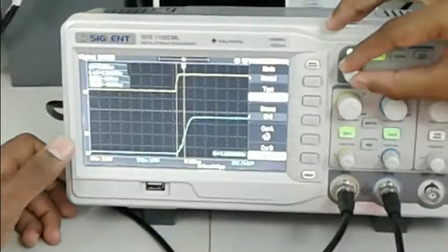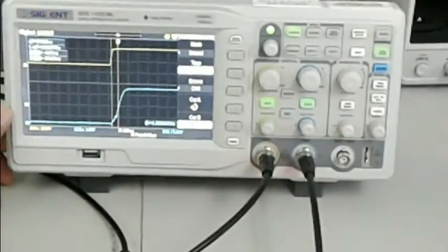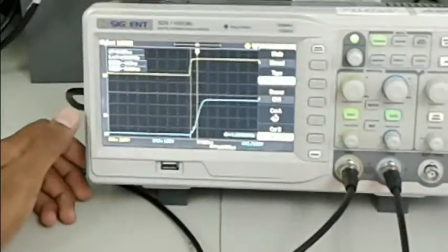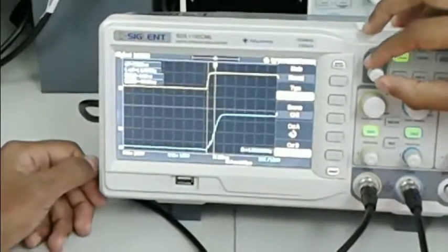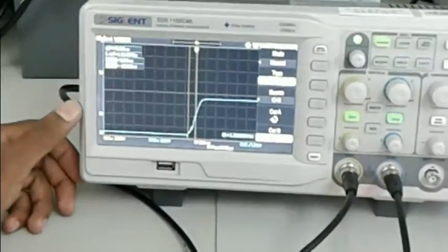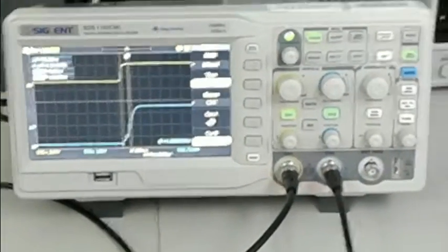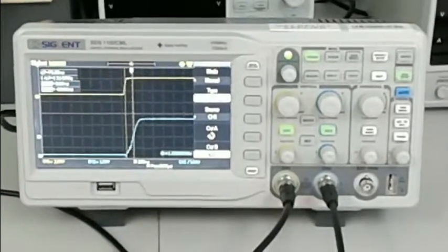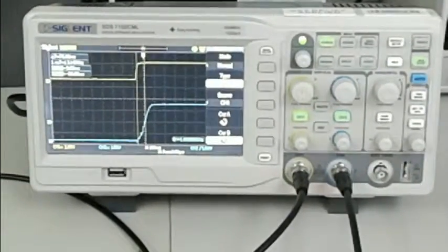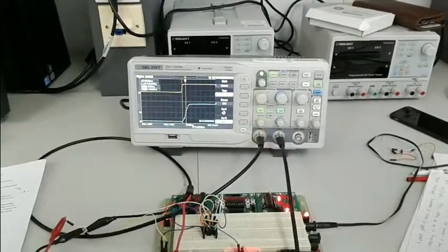It must be behind the y-axis, and therefore we get a result of 76. So that's the change in time, the total propagation delay for the high edge graph. For further calculations, we divide it by 4 to get the propagation delay.